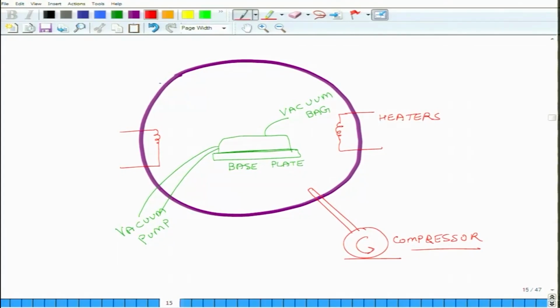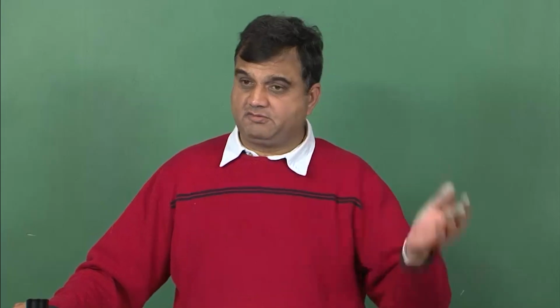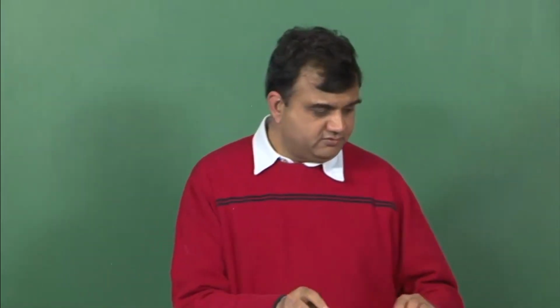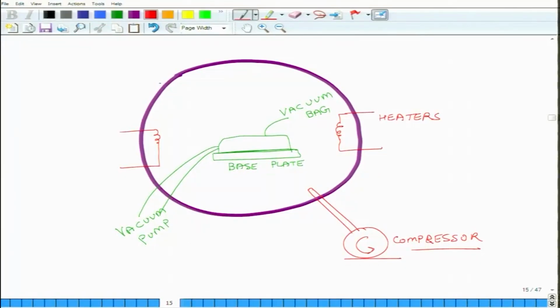So, the part gets cured quickly, and because of the presence of vacuum as well as of this pressure, all the air and porosity gets minimized. Here again this is less expensive because you can use the same autoclave for all different types of parts as long as the part can fit in the autoclave. Even if you have to make a big aircraft wing, you can make a very large autoclave and you can put several aircraft wings in it and produce the same part continuously. So, this is what the autoclave bag molding process is all about.